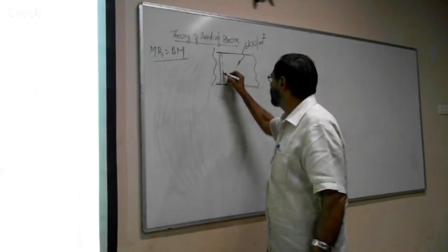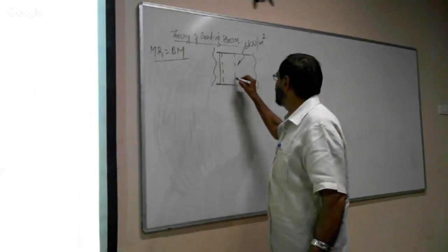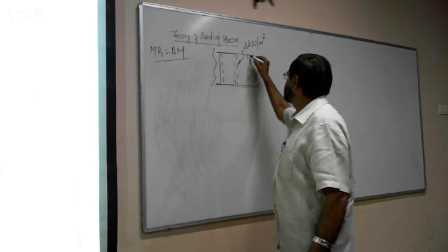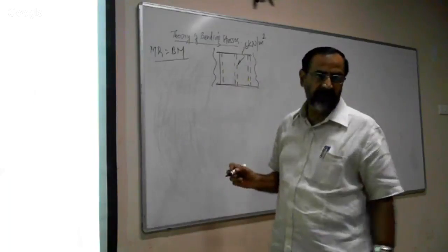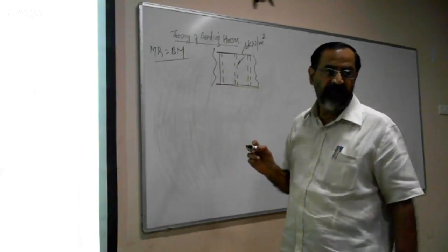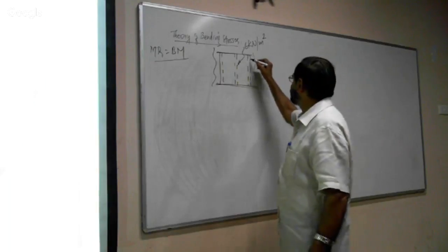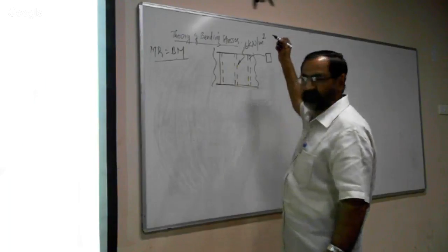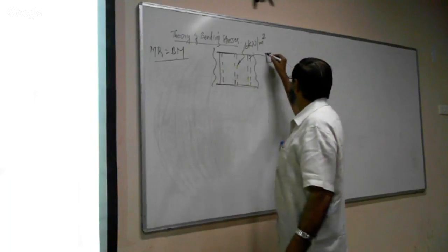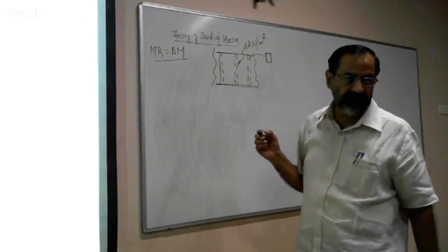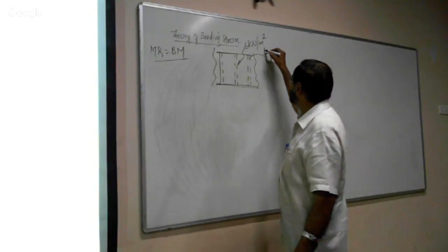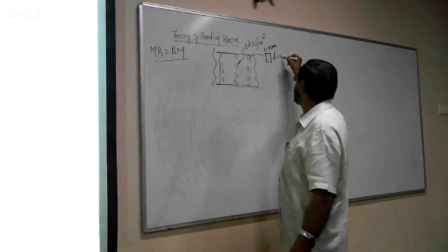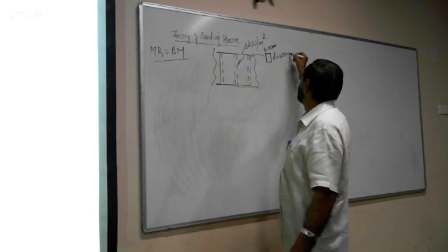These below the floor are the beams. Timber joist means timber beam. The section of this beam is like this. They have given the section of the floor beam: the beam size is B equal to 100 millimeter, and depth D is equal to 400 millimeter.